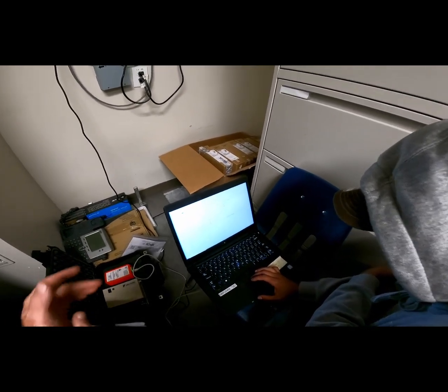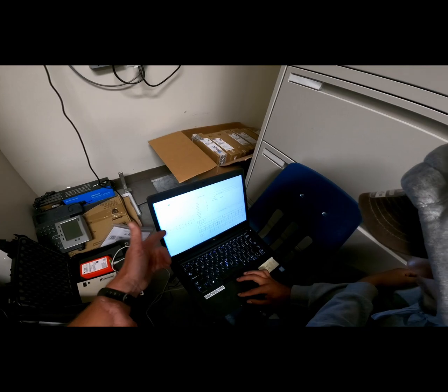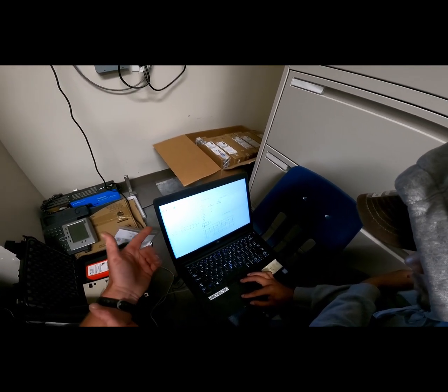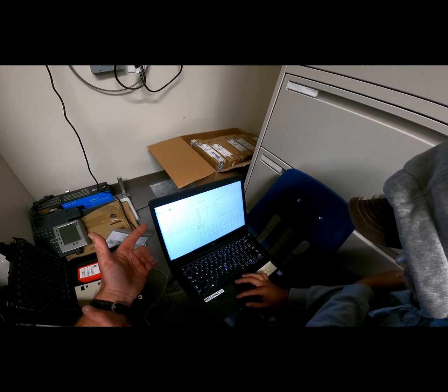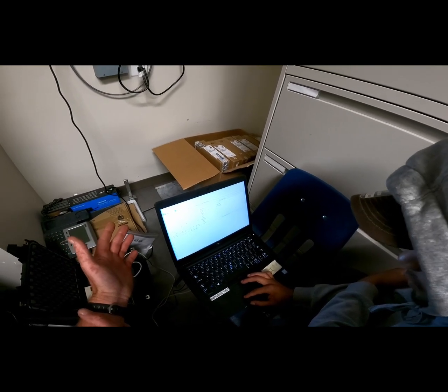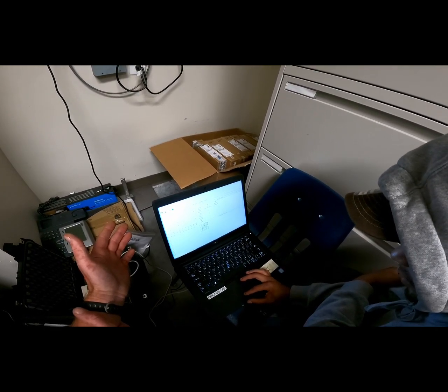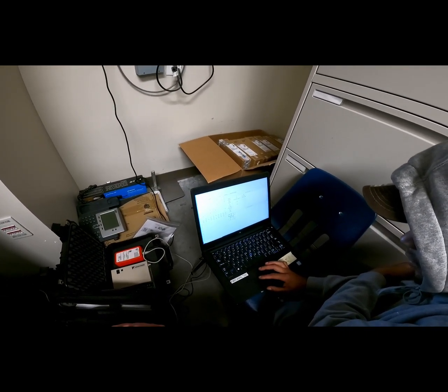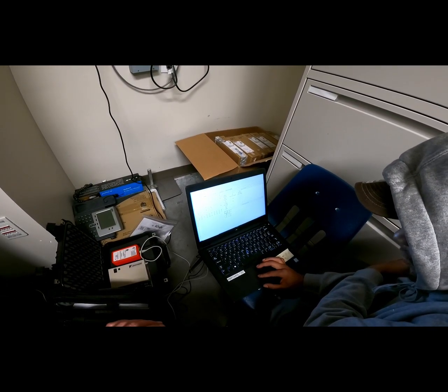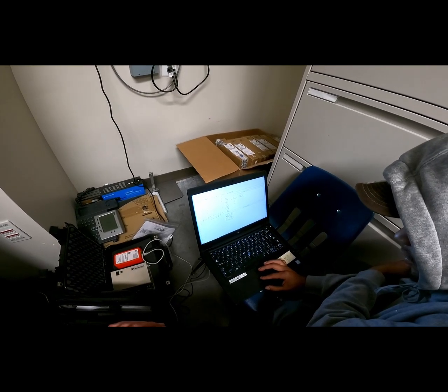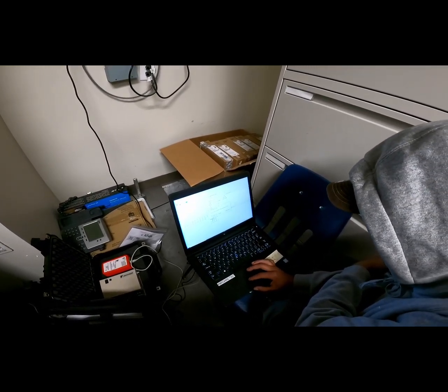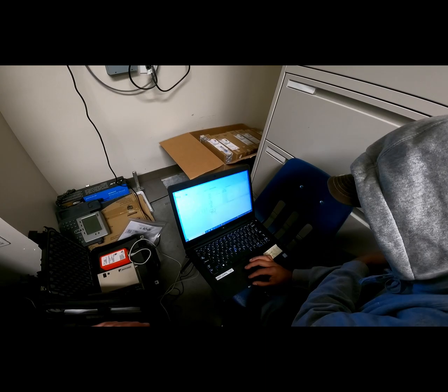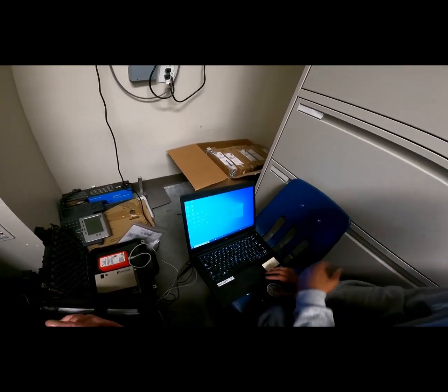And that's it. Now you're back in the initial screen where it shows you all the units. If you wanted to monitor another one, you could, but we don't have any error codes, and we can't troubleshoot something that doesn't exist at this moment. So go ahead and hit file and return. Don't save it, we've already saved our monitor mode. And that's all you've got to do.